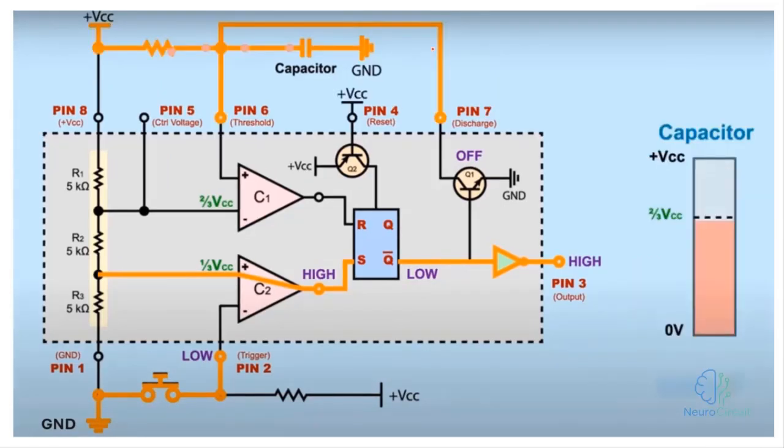Look at this part here. When the button is pressed down, it causes my output to go high, the transistor turns off, and here, when the transistor is off, no output from the transistor is sent to pin 7. In this state, pin 7 is connected to pin 6, and on the other side, pin 6 is connected to VCC through a resistor. Look at these pink circles here. This is the same current that causes the capacitor here to start charging from the VCC. See, it's like a circuit where the capacitor here is being charged by a power supply,